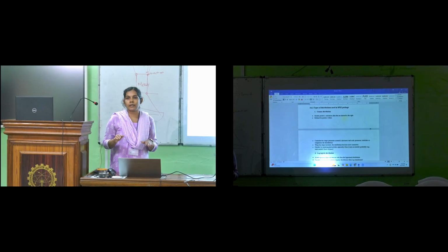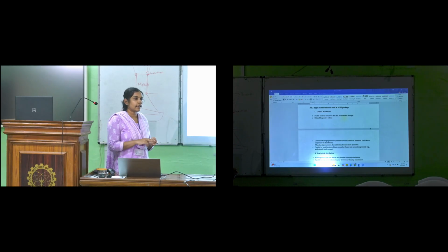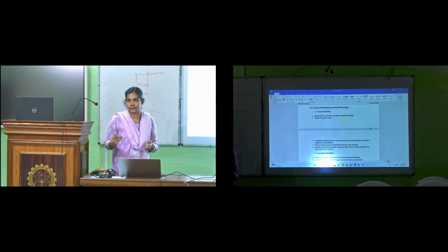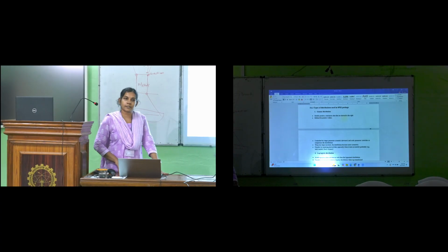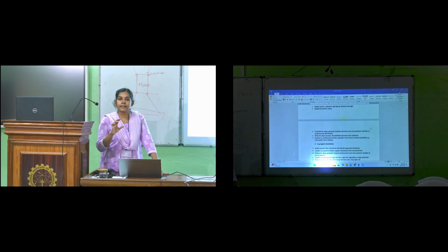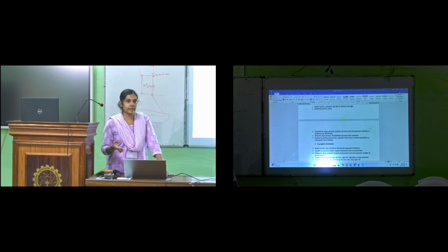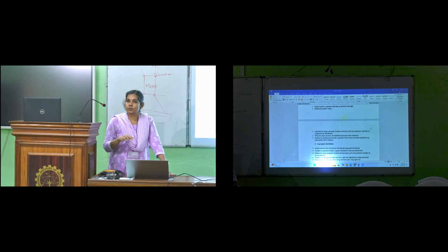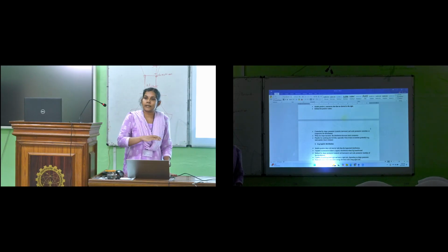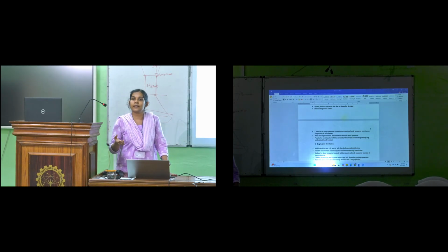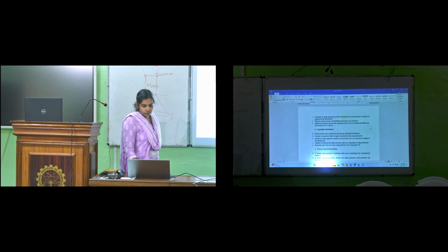These are the most commonly used meteorological drought indices: the standardized precipitation index and the standardized precipitation evapotranspiration index. These two indices we can calculate using the SPEI package in RStudio. The major difference between these two indices is that for SPI we use only precipitation data, and for SPEI we use both precipitation as well as temperature data. We convert that temperature data into potential evapotranspiration, and that potential evapotranspiration is used for the calculation of SPEI.